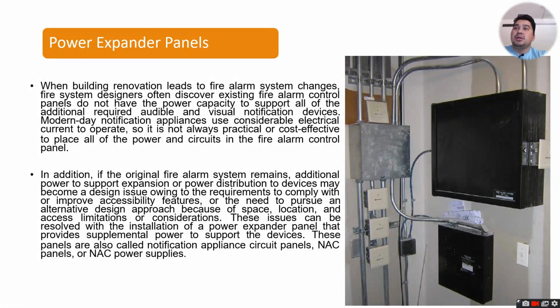Power expander panels. When building renovations lead to fire alarm system changes, fire system designers often discover existing fire alarm control panels do not have the power capacity to support all of the additional required audible and visual notification devices. Modern day notification appliances use considerable electrical current to operate. So it is not always practical or cost effective to place all the power and circuits in the fire alarm control panels.